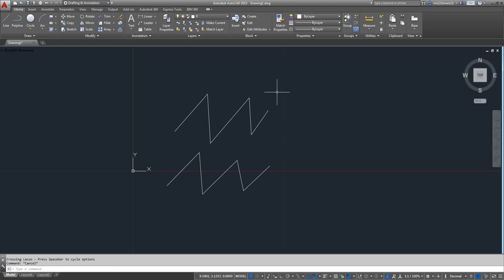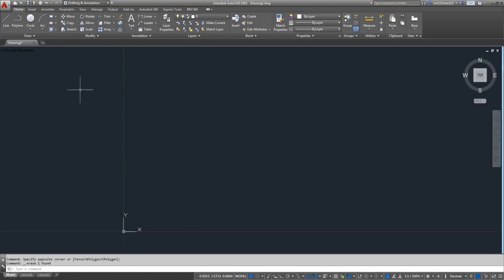Okay, now we know how to make lines, but when we are making lines, we need a real length. So we are going to select line, and you can see, for example, if I want to make a line, I have different angles. So if I don't want different angles, I want to be straight, what we can do is go right over here and activate the ortho mode or press F8. So you are going to be able to make straight lines like this. And now what we can do is put different sizes. For example, 5, enter, and then that line is 5.